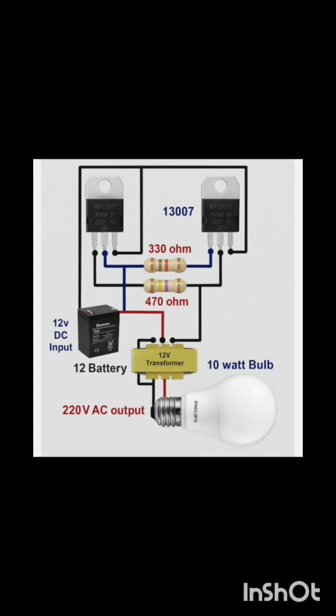Oscillator circuit, which generates gate pulses to control switches. Switching circuit will alternate current direction through the transformer winding. Next, the transformer will step up low DC voltage to high AC mains voltage. Filters like capacitors or inductors smooth the waveform to reduce harmonics. Finally, the AC output is the final usable alternating supply.